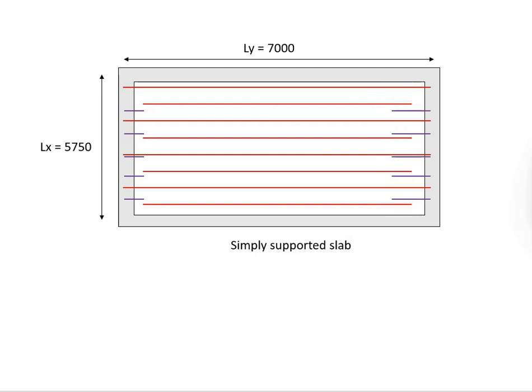You have one more issue here. We discussed the principles of doing lapping of the reinforcement in our previous videos regarding the curtailments of reinforcement bar in continuous beam. For stress to effectively develop from 0 to the full stress, a full lapping length will be required.